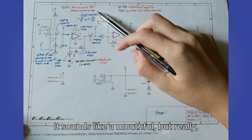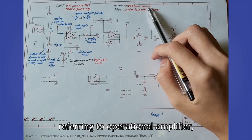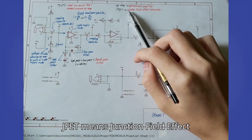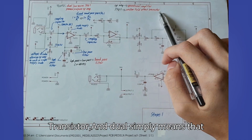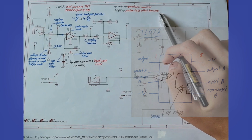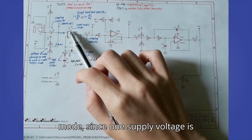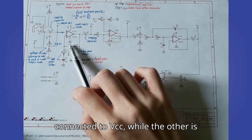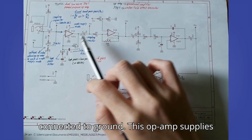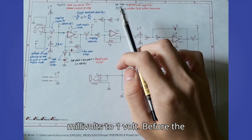It sounds like a mouthful, but really what it's trying to say is that op-amp is referring to operational amplifier, JFET means junction field effect transistor, and dual simply means that there are two op-amps within the IC. The op-amp is operating on single supply mode, since one supply voltage is connected to VCC, while the other is connected to ground. This op-amp supplies a voltage gain, somewhere between 10 mV to 1 volt.